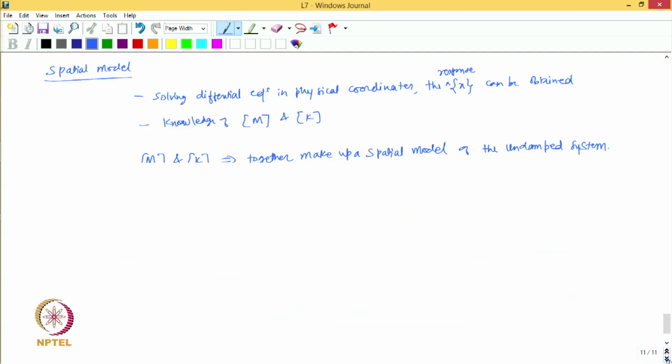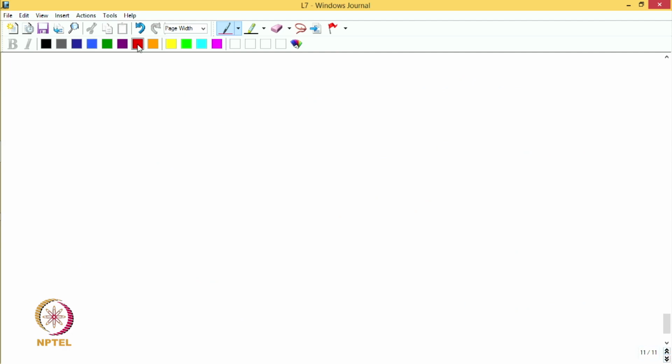So, therefore, we can represent the relationship using this simple block diagram and say that if I have the model, I can find the dynamic response for the given excitation force, and this model consists of the eigenvalue matrix and a mass normalized eigenvector matrix, right.